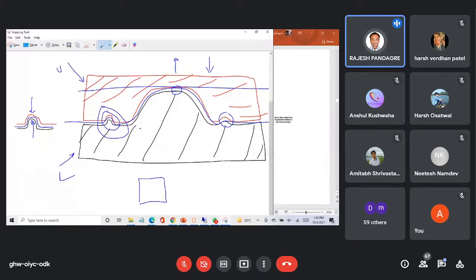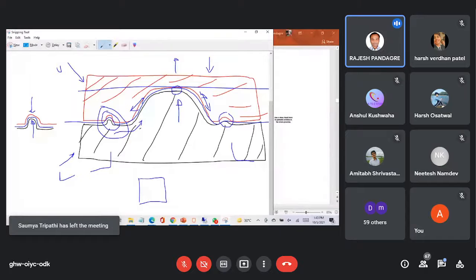Let's say you hold with both hands here, and push this from here. What will happen? If you hold it tightly, it will start stretching. In this area, stretching is happening. And if you have more gap here, the material will flow in this direction also. So two things are happening basically: one is locking, and one is flowing also. So we call it lock and flow bead. This is the fundamental function of this draw bead.